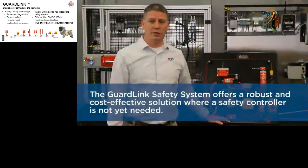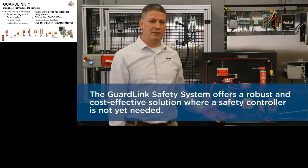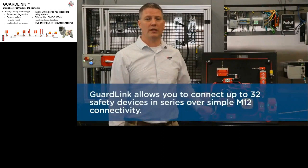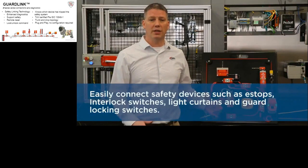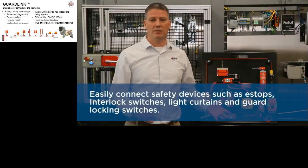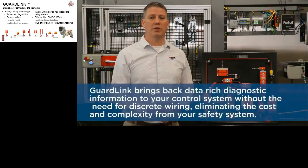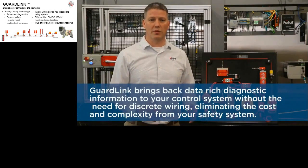For smaller and simpler applications where a safety controller is not yet needed, the GuardLink safety system offers a robust and cost-effective solution. GuardLink allows you to connect up to 32 safety devices in series over simple M12 connectivity. You can easily connect safety devices such as e-stops, guard locking switches, interlock switches, and light curtains. GuardLink brings back data-rich diagnostic information to your control system without the need for discrete wiring, eliminating cost and complexity from your safety system.